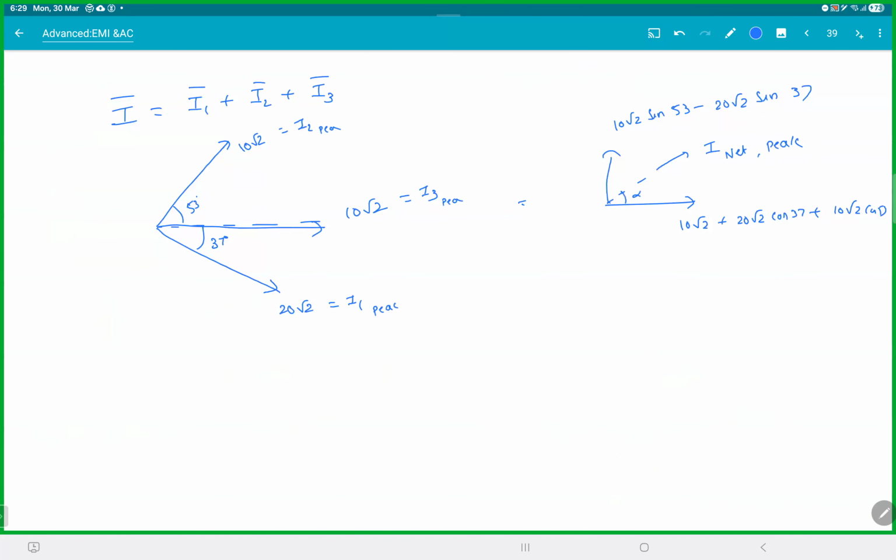What about the net impedance? That is the easiest thing now. So Z bar for the whole circuit is V bar by I bar, isn't it? So this will be V RMS of the whole thing, and this is the I RMS of this whole thing, and you're done. Since you know the current from the source and you know the voltage of the source, divide them and you'll finish it off.